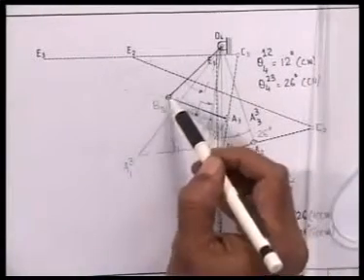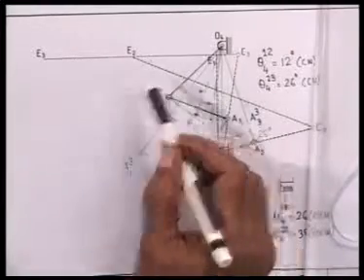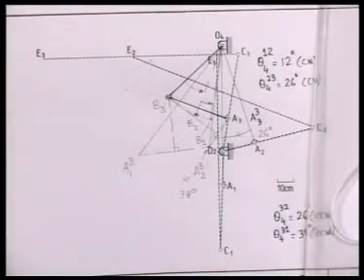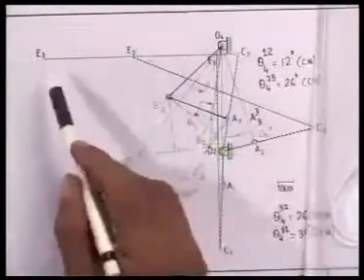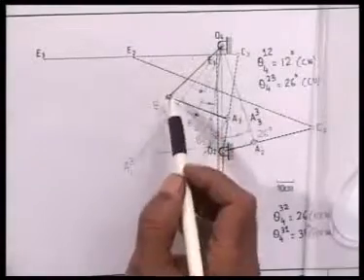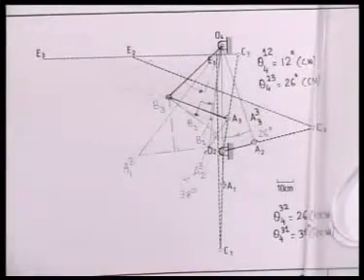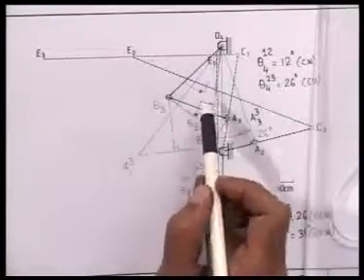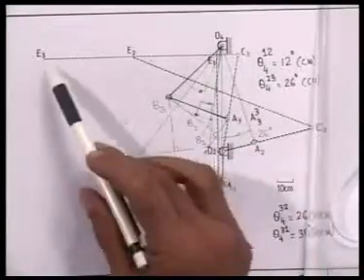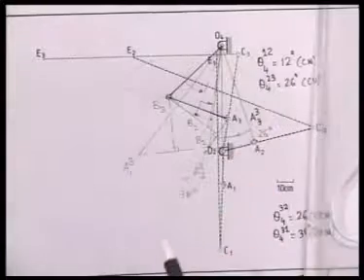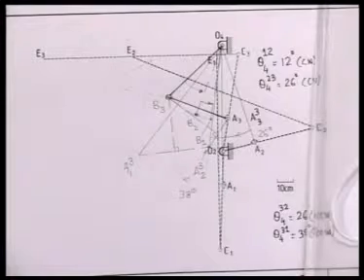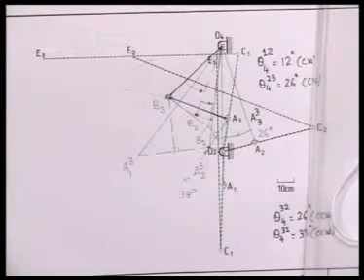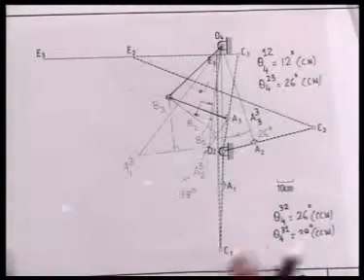To locate the hinge on the door board D, I have to hold the door board fixed, because BD length is a constant length. So if we hold link 6, that is the door board fixed, then B goes on a circle with D as center. So we make a kinematic inversion holding the door board always fixed at its third position. To obtain the inverted position of B2 and B1, we use our procedure of kinematic inversion and use a tracing paper.